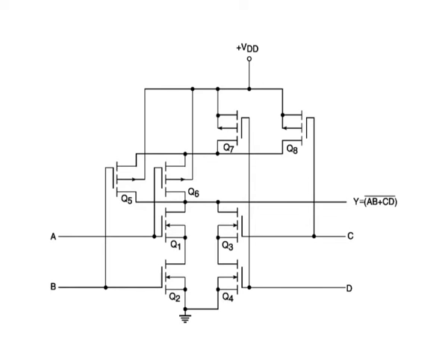If these conditions are applied to the circuit of the figure, we find that the ground will remain disconnected from the output and also that there is always a path from VDD to output. This leads to logic 1 at the output. Thus, we have proved that the given circuit implements the intended logic expression for the AND-OR-invert gate.